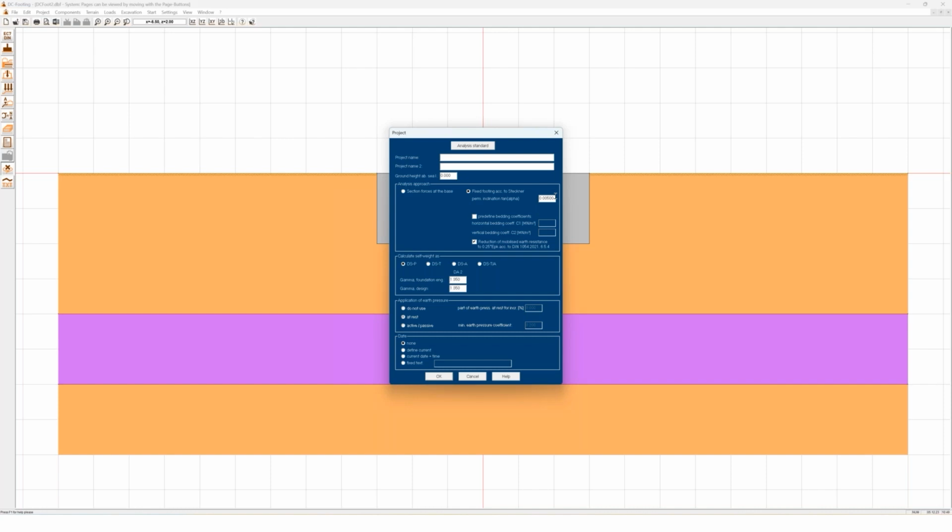And for the stability verification, an ultimate bending moment is determined. This ultimate bending moment is the result of all forces applying on a footing due to the inclination, the rotation. So this includes active and passive earth pressure, bottom friction, soil pressure, and this ultimate bending moment will be compared with the applied bending moment. So yes, this is the actual method.